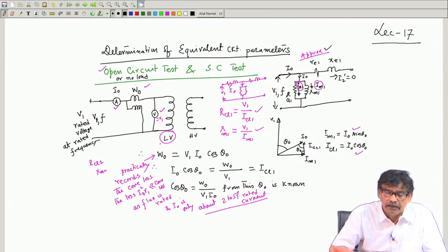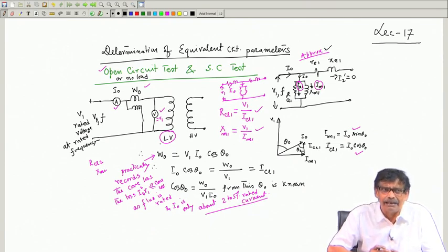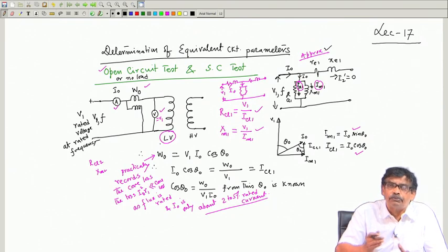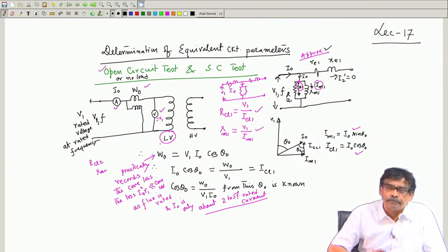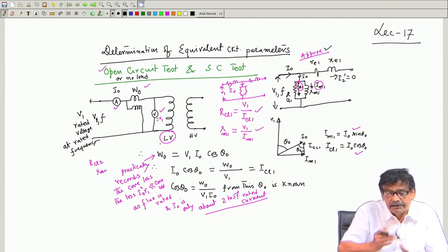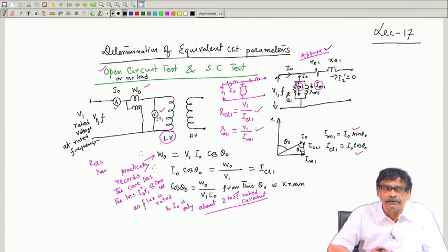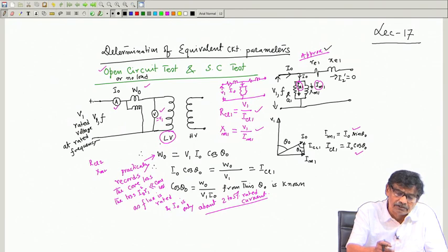That is important. For example, if the no load current you calculate comes out to be 0.8 ampere, expected to be of that order, then you connect an ammeter which can record current up to say 1.5 ampere; that will be a good choice. Similarly, the current coil of the wattmeter should be of the order of 2 ampere range. Of course, a 5 ampere range ammeter and a 5 ampere range current coil of the wattmeter will do, but accuracy will be better if you use lower ranges of ammeter and current coil rating of the wattmeter. The pressure coil rating of the wattmeter is of course the rated voltage of the transformer.